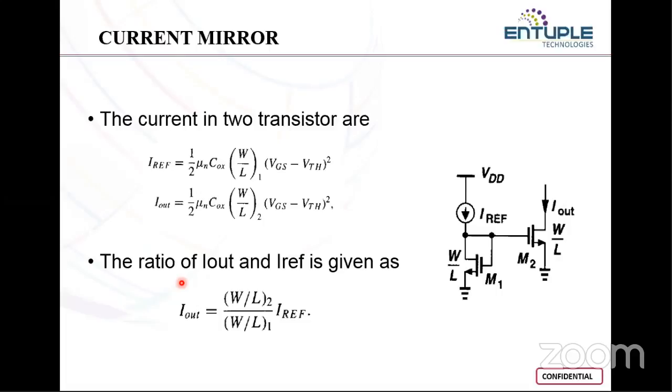When the width is more, the charge carriers have more opportunity to flow. It will be determined by the RC time constant. When we are talking about MOSFETs, it will be mostly dependent on the width of the device. R will change depending on the width. Also, C will change, I mean, the area will change. So depending on the width, C will change automatically. Exactly, RC will change. So it is also dependent on the RC time constant.